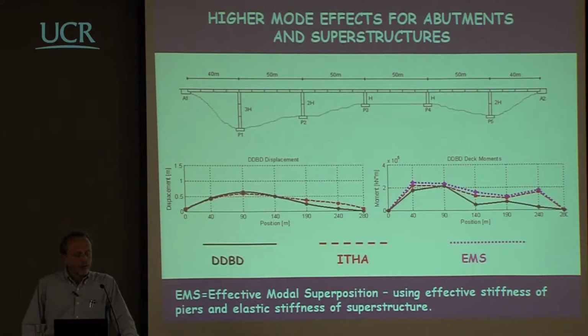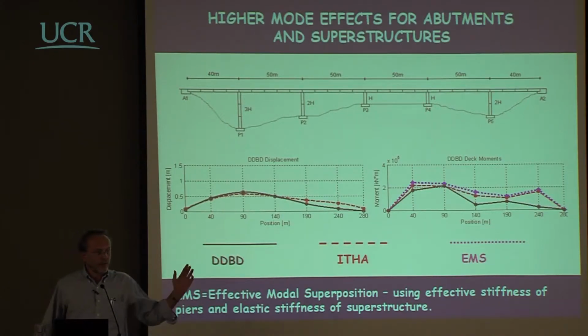Now, looking also at one of the last slides that Nigel was showing, the problem of the transversal response of a bridge, possibly of a very irregular bridge, something where you can have some short pier in the middle, or on one side like here, and therefore you are somehow making some error when you are trying to guess what the top displacement should be here.